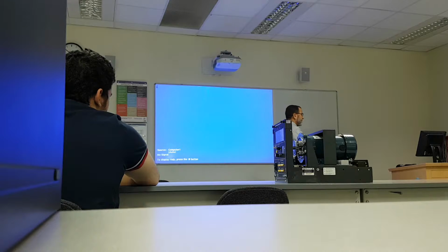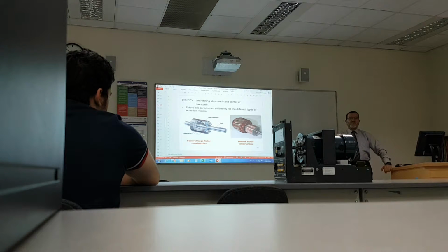Because again, if you look at systems, their power factor doesn't stay the same all the way through. It also depends on what equipment they're running, what time of day, what kind of production scenarios they're going through. So that's the main advantage of synchronous motors. More expensive than capacitors, right? Because you've got moving parts, you've got maintenance. But that's a decision that has to be made at the design stage. Do we use capacitors or do we use synchronous motors?